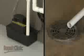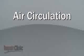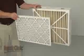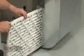Condensation often builds up in the exhaust pipe of high-efficiency furnaces. For this reason, a condensate pump or floor drain is needed. The most important factor in efficient furnace operation is air circulation. To ensure proper air circulation, the furnace filter should be checked monthly and replaced as needed. There are several types of filters available and range from 1 to 5 inches thick. The filter can be installed into the slot in the return or in an air cleaner.